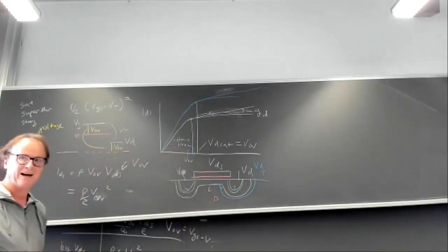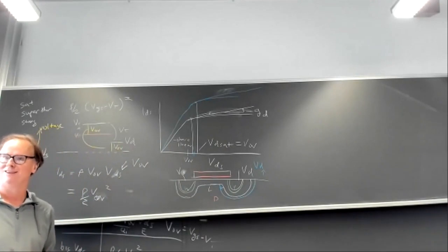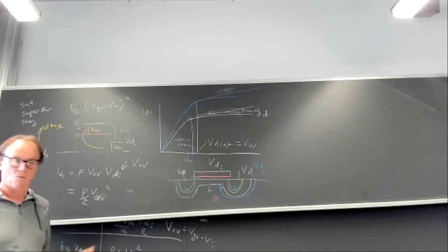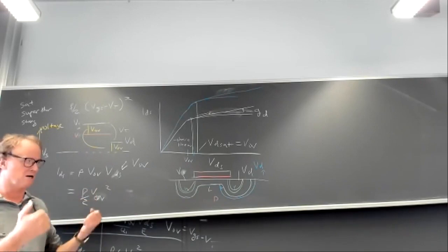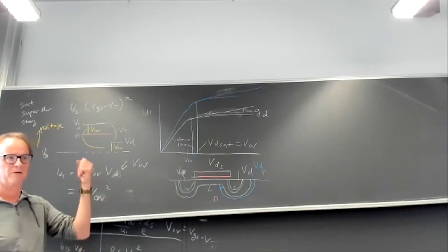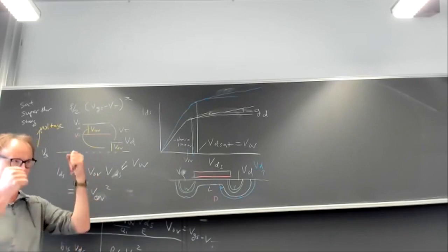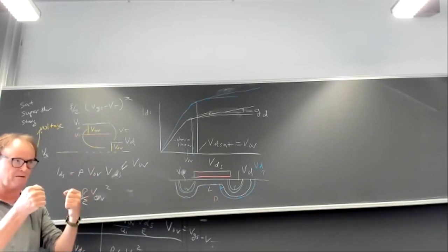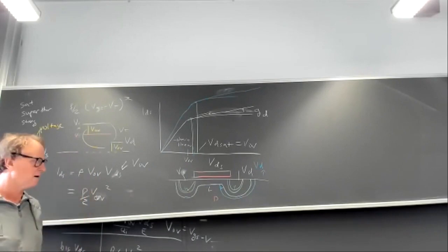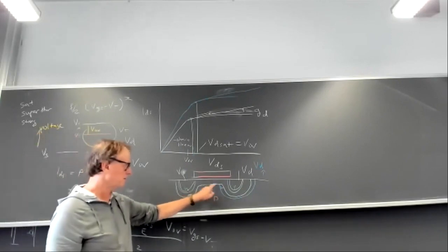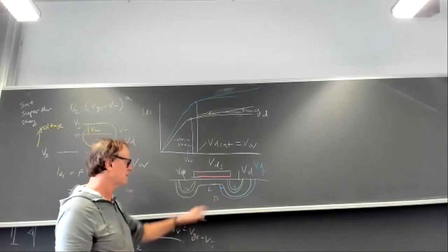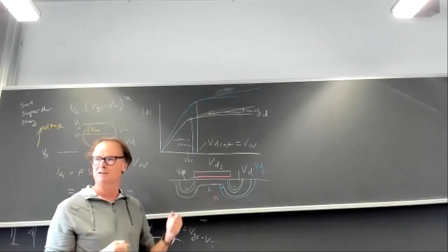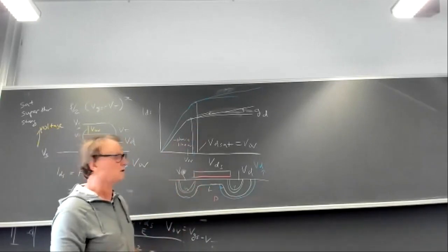And do you remember this factor of 1 over L? The shorter the transistor, the bigger the electric field. Or in subthreshold, as you'll see next week, the shorter the transistor, the bigger the concentration gradient, right? Because you have the same concentration ratio but shorter length. It's going to make a higher gradient. Either effect, increasing electric field or increasing concentration gradient, both increase the current. And so that's why there's a slope on this curve.